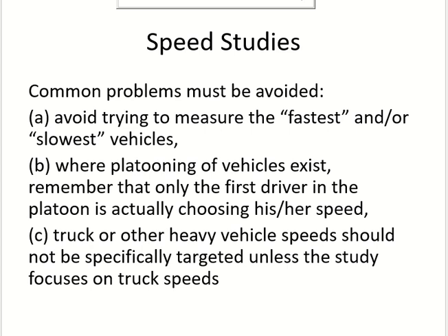These are some points which are related to speed studies, and you have to keep them in mind when you will be doing the speed study for your term project. Okay, I'm talking about the second submission now. The second submission, speed study is a part of it. Okay, so while you will be doing a speed study at that time, you have to keep these things in your mind. The first thing is avoid taking data for the fastest or the slowest vehicle.